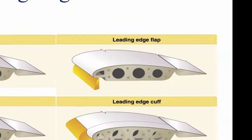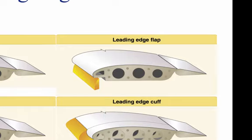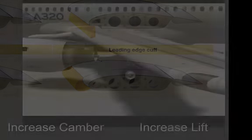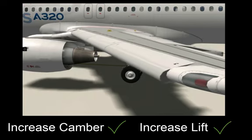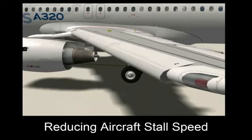Leading edge flaps work to increase the camber of the wing and are commonly used with trailing edge flaps to reduce the nose-down pitching tendency. Leading edge cuffs work to increase the wing's camber and lift. The front edge of the wing is pushed down and forward, allowing for more air to connect with the upper surface of the wing at higher angles of attack, thus reducing the aircraft's stall speed.